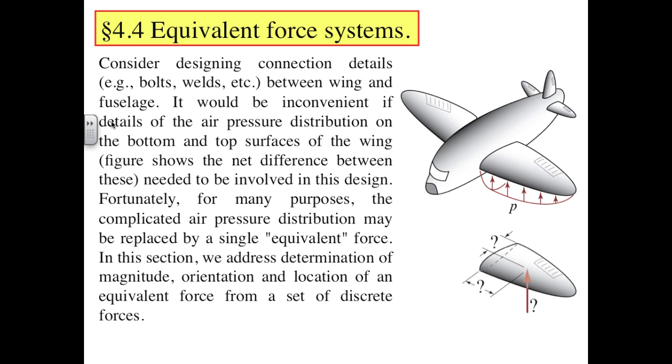Up until now, we've treated weight as a discrete load, but mass is a distributed quantity, and weight is actually the sum of all the incremental weight contributions throughout a body. We could write the weight either as the total mass times gravity, knowing where the effective center is, or we could write it as the sum of these incremental contributions, the integral over the volume, rho, which is mass density.